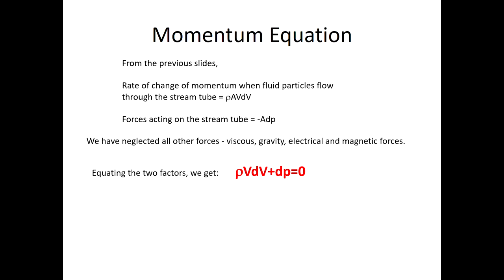For example, inside a control volume, if we have a propeller, it may be accelerating the flow. If we have a little wind turbine, it may be decelerating the flow by removing the energy. So those are also distributed body forces. Compressor, turbine, none of them are present in our control volume. Here no body is present, no rotating, moving body. So this is where we use it, usually when such things are not present.